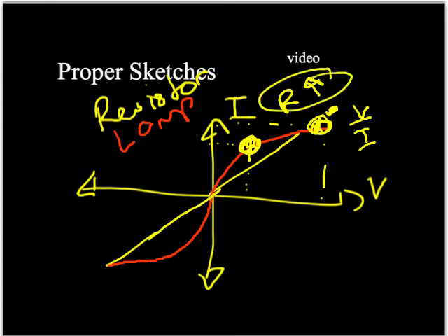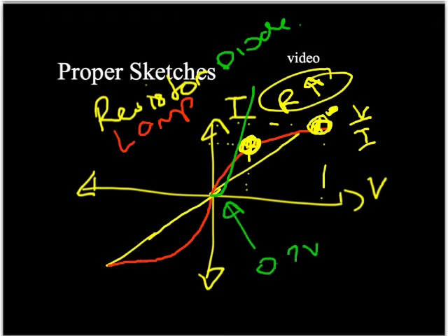And the last one you'll draw will be the diode. Now that one there will go along at 0 for a bit and then suddenly increase. Usually that's around about 0.7 volts depending on the diode. The other way though, when you connect the cell around the other way, it will go along at 0.